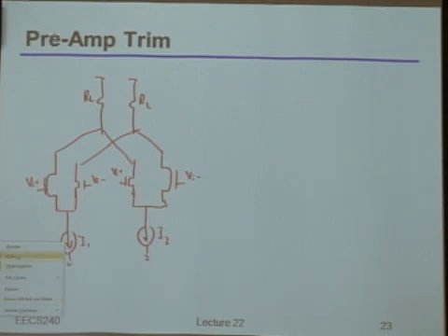So just in case people are interested, this was first proposed by a guy named Brian Casper, and I believe this was published in JSSC, if I'm not mistaken, in around 2002 or 2003. I don't 100% remember, but if you do a search for it, I'm sure you'll find it. This is sometimes referred to as a Casper DAC. And it was actually used in exactly the same context you guys are interested in, meaning it was used as a way to cancel the offset of a comparator inside of a high-speed serial link.